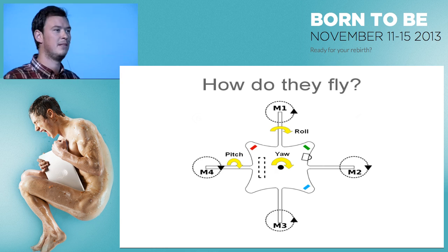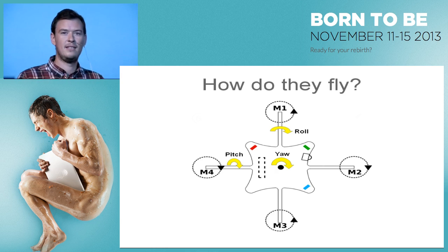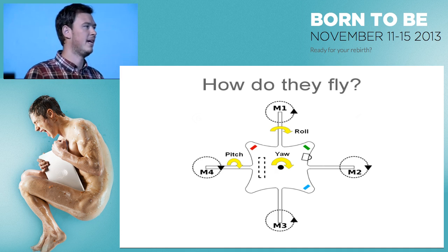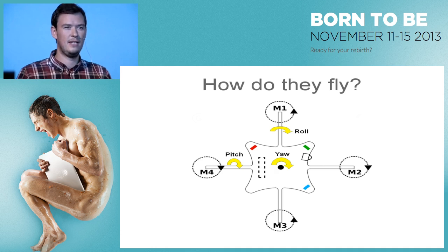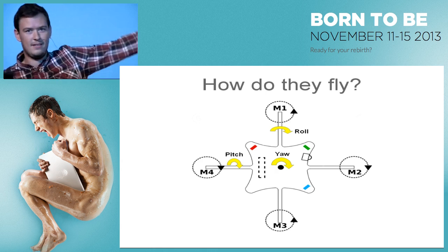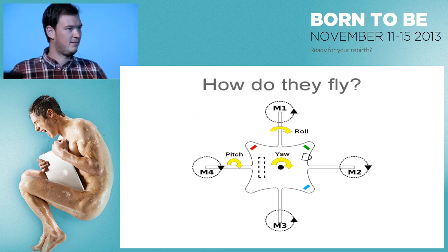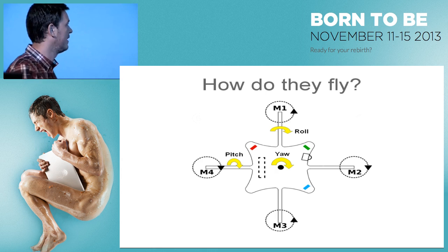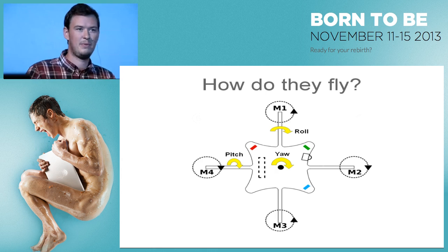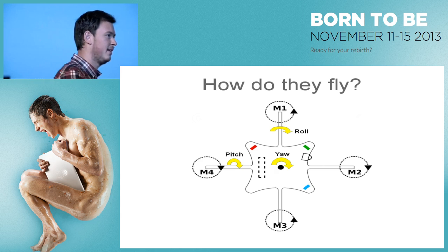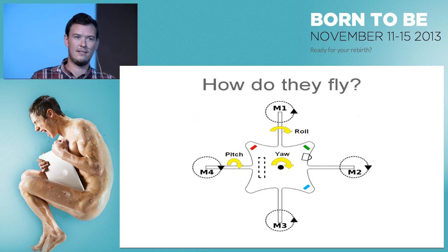Maybe a lot of you already know it, but to move around in the room, you need to control the attitude. The attitude is roll like this, pitch when you go up and down, and yaw when you turn around yourself. For that, it's pretty perfect to have 4 motors, because you can lock them into each axis.